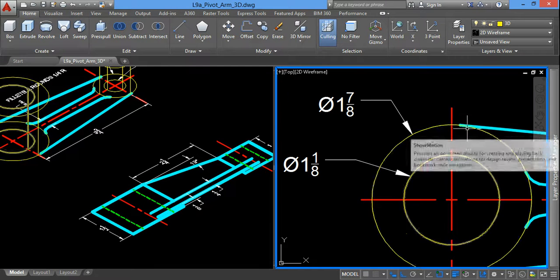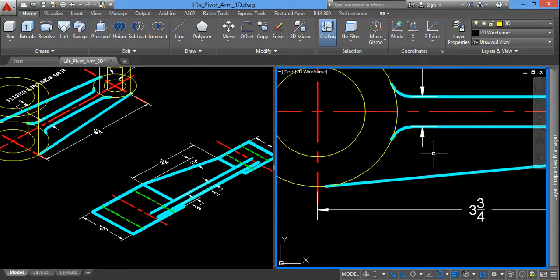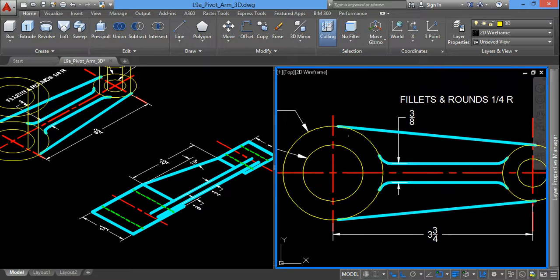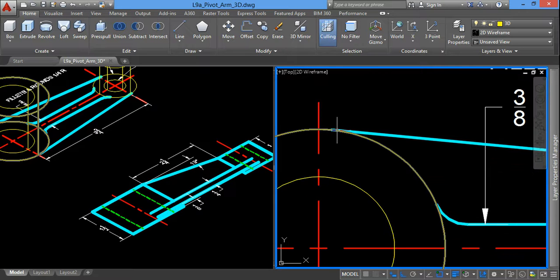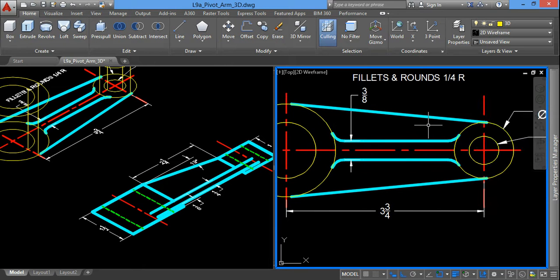It's based on the tangent of that circle and line. If by any chance you had drawn yours incorrectly, in which the inclined line intersects with the center line and the circle, you may want to redraw those features.